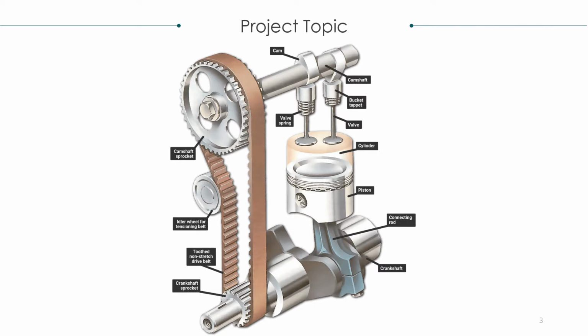The subject for research is a cam belt or a timing belt of an internal combustion engine. Timing belts are different from normal flat belts because they have a constant transmission ratio, not dependent on torque. This is due to the fact that the mechanism of power transmission is geometrical interference and not a frictional one. Thanks to this property, the type of belt is also called synchronous, and it's suitable for applications in which sliding is not acceptable, such as for moving a camshaft in an internal combustion engine. This also makes it an interesting topic to analyze regarding vibrations.